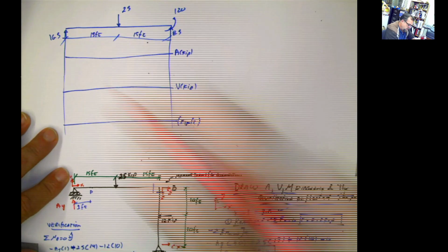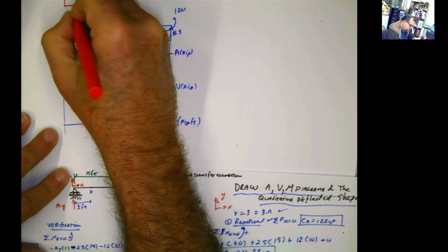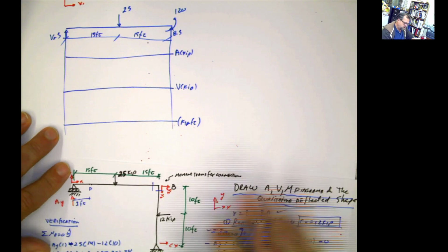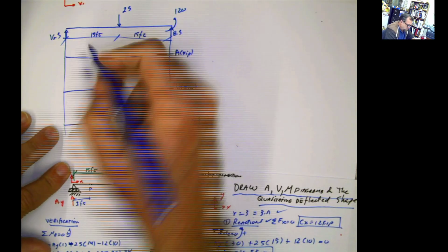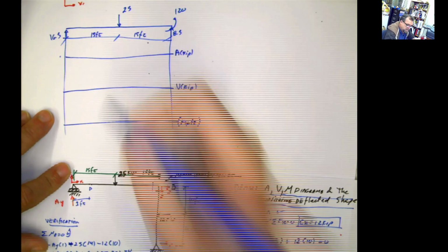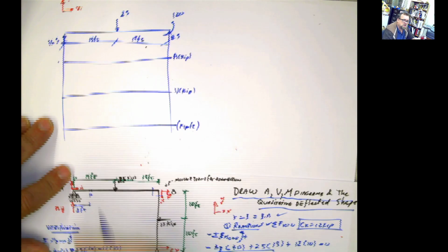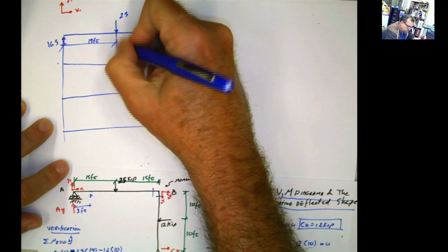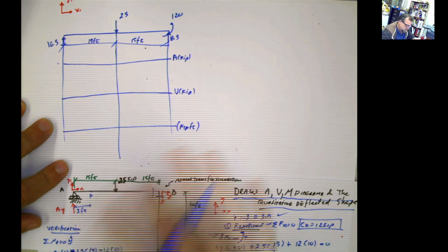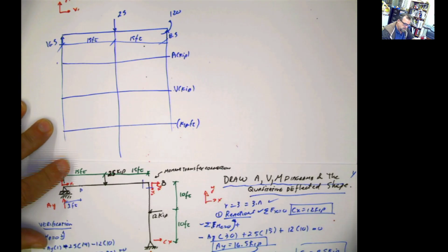And my coordinate system, local coordinate system, is this one. So I start with the axial. Do you have any axial here? And remember, this is the baseline. This defines the 0. And remember, you have to draw vertical lines also at the beginning and the end. Wherever you have a concentrated force, you define your points of interest, your regions of interest, and you do that.